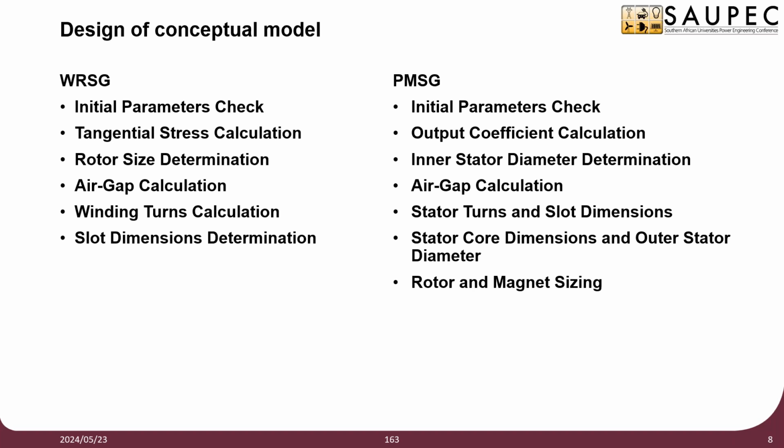For the WRSG, the tangential stress was calculated based on the machine specifications. The rotor size was determined, allowing for calculations of the machine length. The air gap was calculated, determining the stator size. The turns were calculated using a winding factor according to the machine specifications.